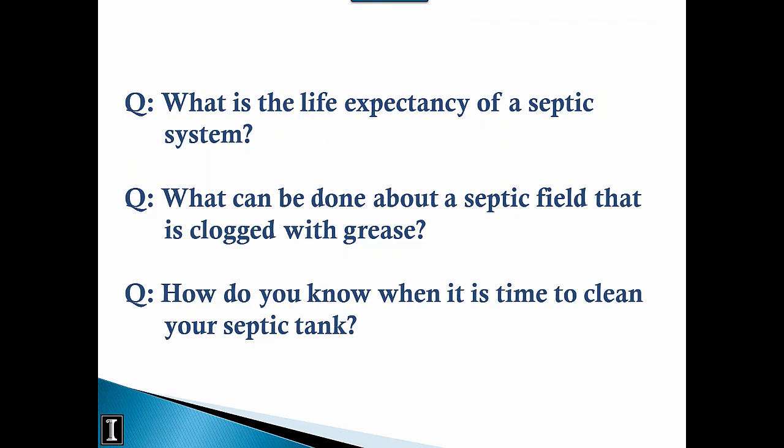So it really depends on, I think, 2 factors, which would be the installation and the planning that went before the installation. Most importantly, the depth to groundwater, how far between the bottom of that septic leach field where the water is released to where the highest groundwater table is. You want to have a national minimum of 2 feet. Here in Massachusetts, the minimum is 4 feet, and a lot of boards of health have actually gone to 6 feet, depending on their soil, especially down at the Cape where it's very sandy. So it really depends on the installation, the oversight during that installation, as well as what you've talked about quite a lot, which is the use.